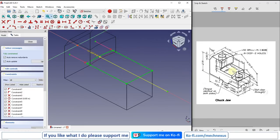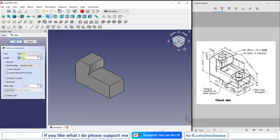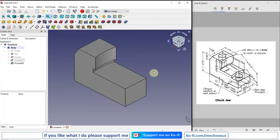So our profile is closed, and now our depth here is 0.31 inch, so I will close it and I will switch to the flat lines. Now I will go for the cut and I will give dimension 0.31, and I will say OK.